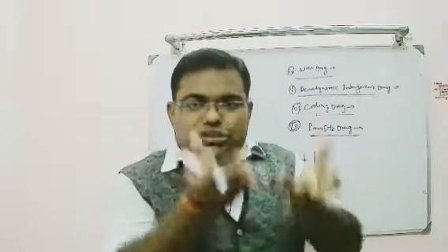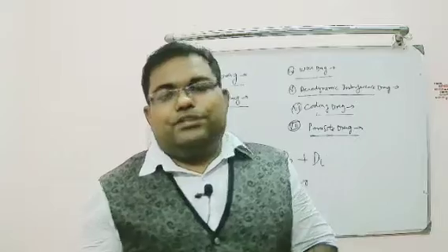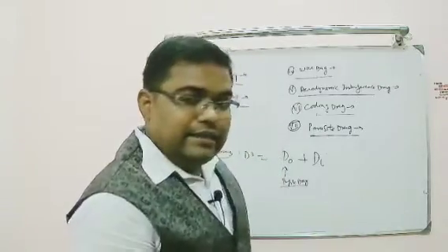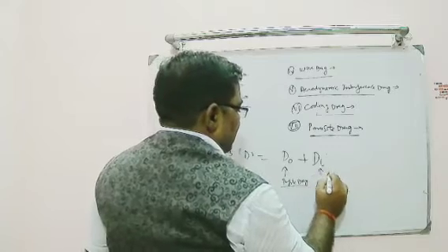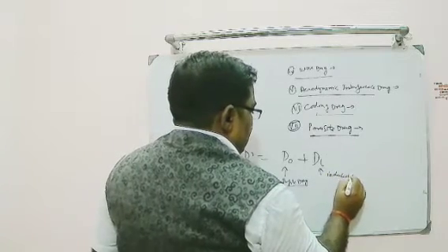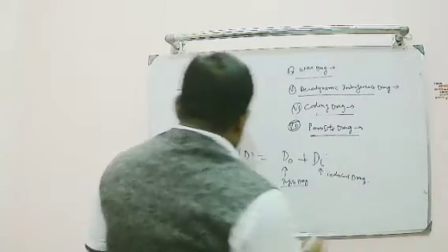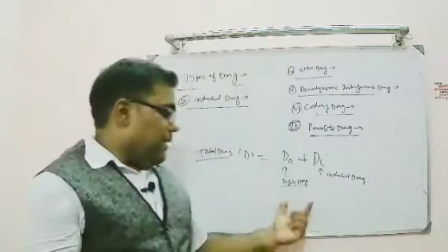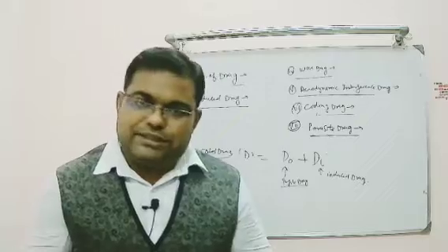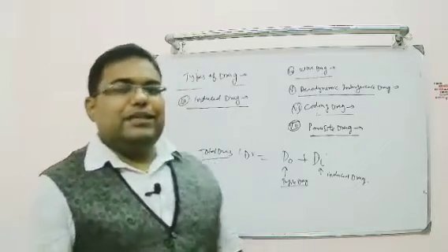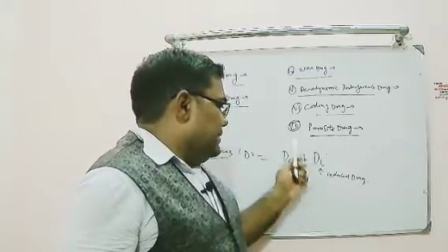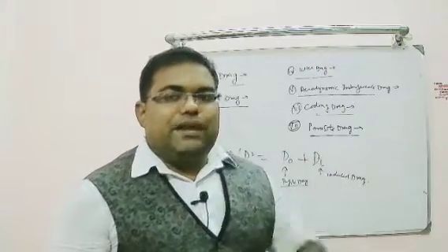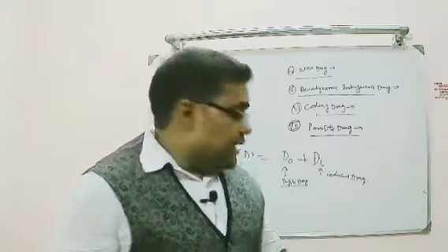Interference also depends on the geometry. Shock wave formation also depends on geometry. So the drag due to geometrical features is the profile drag, and the second is induced drag. If you look at the contribution, usually when we do the calculation, you will come to know that the profile drag contributes 15% of the total drag, and the rest, 85% of the total drag, is due to the induced drag.